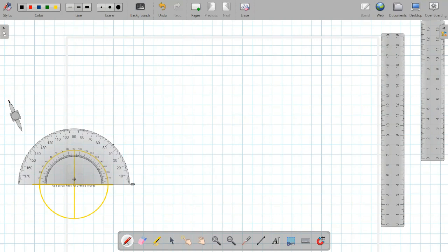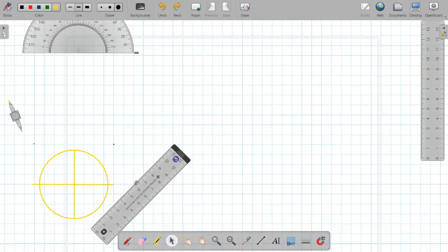So just marking 45 degrees at this particular point and this particular point from this side. If I measure, it will come around here. Now, after marking 45 degrees, we have to just connect these lines. So I will connect this dot with the center. Again, things should be very light. And similarly, I will connect this 45 again with the center and extend it towards the other side. This will give me the 8 parts of the circle. Again, I repeat, all these things should be very, very light.